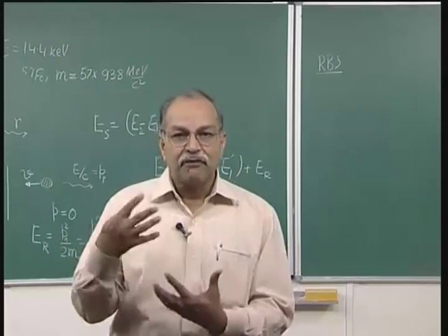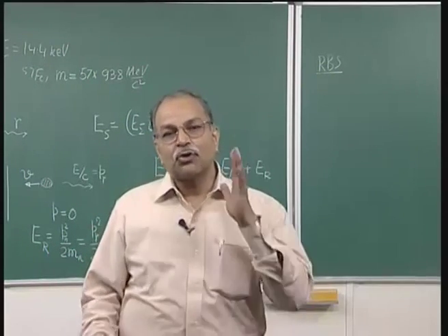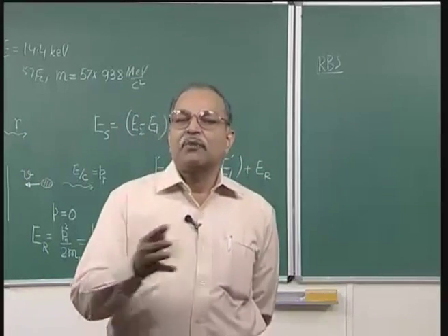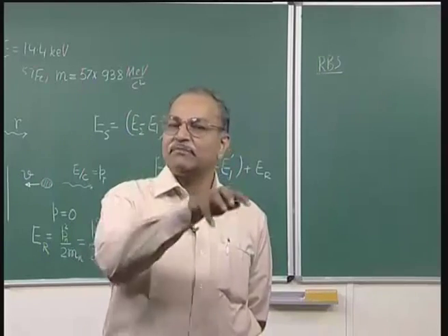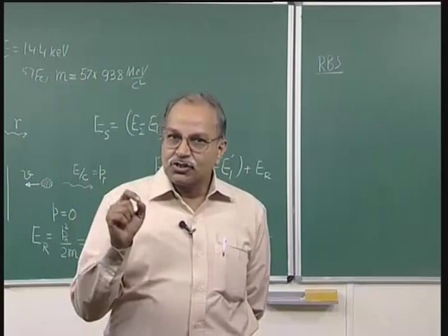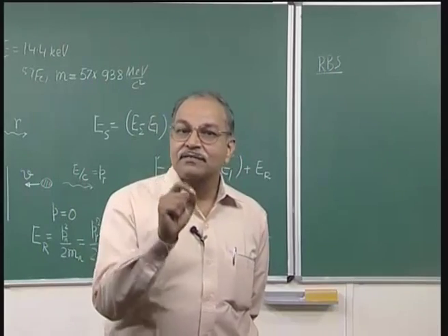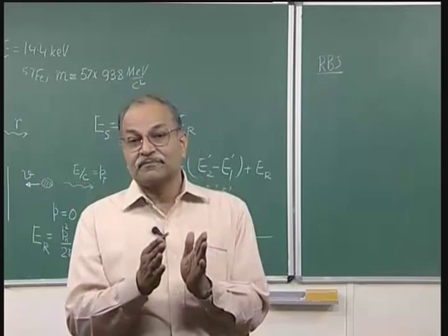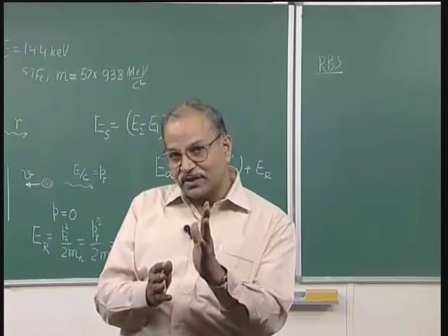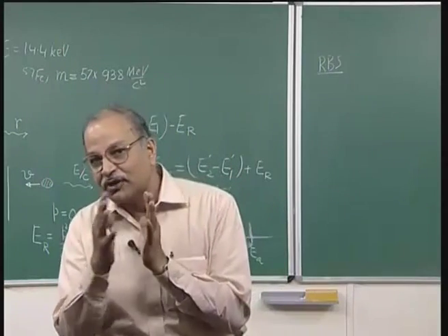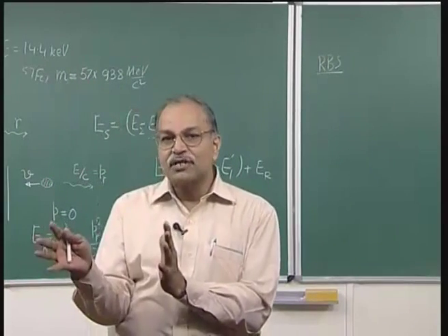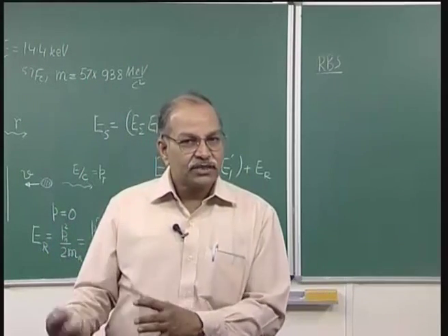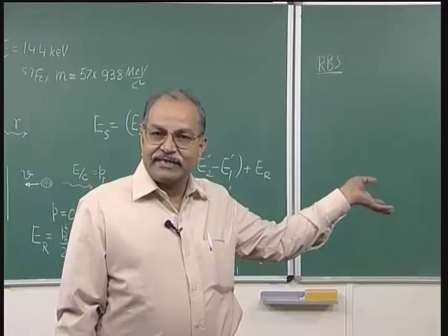So, if you have thin films, or some coating on some substrate, or the substrate itself has, say up to micron depth, some other elements embedded, and you want to know the concentration of those elements in that sample as a function of depth. Right at the surface, what is the composition? If you go say 50 nanometers inside the material, what is the composition? If you want to get that knowledge, RBS is one technique which can be used.